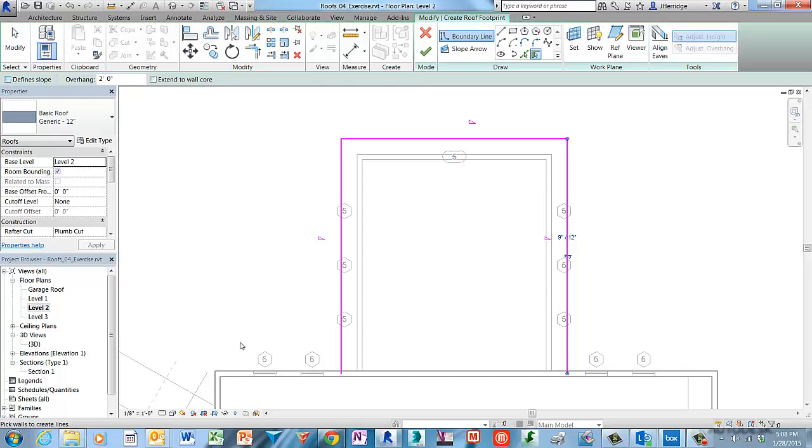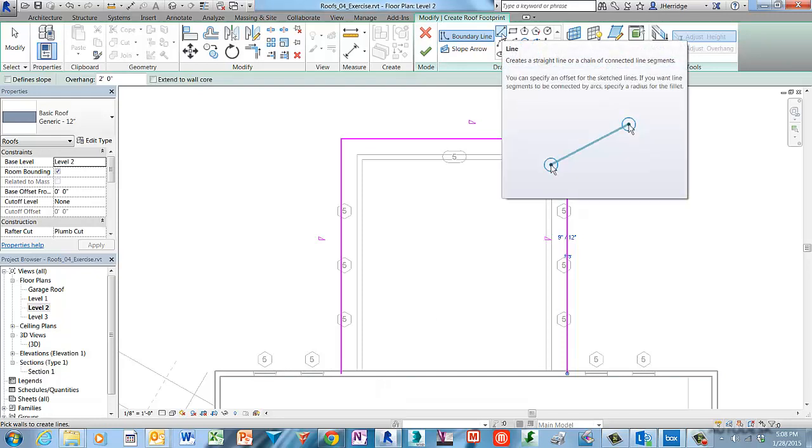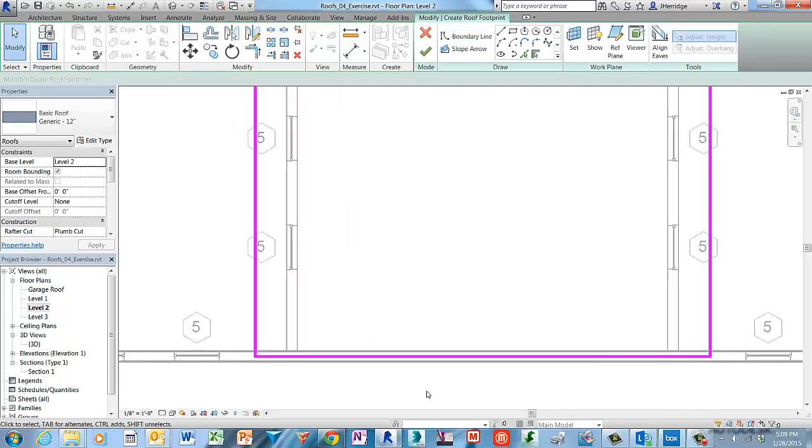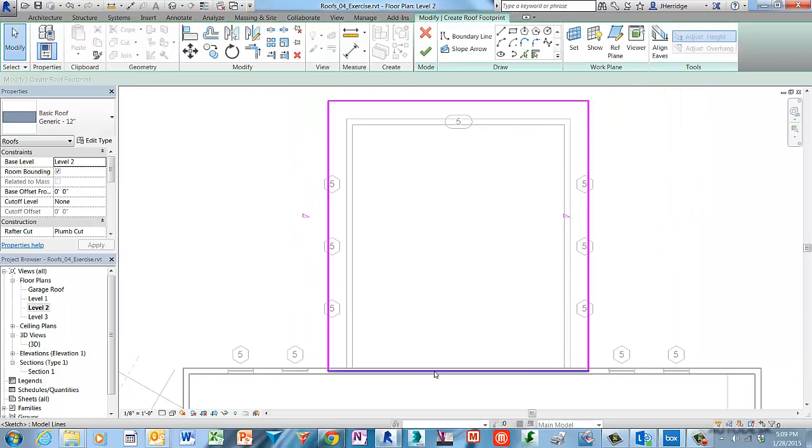Go ahead and remove or unmark the Define Slope property, and we're going to create a closed boundary using a line sketch technique. So just simply create a sketch going from one endpoint to the other. And we just want to make sure that this is indeed a closed boundary. We don't want to have sketch line work that overlaps one another. It needs to be a clean intersection.